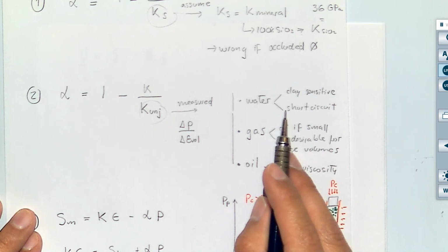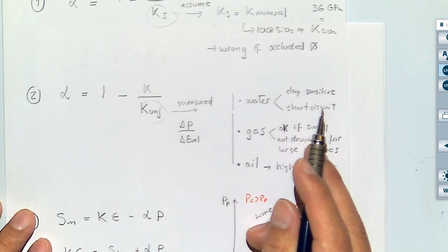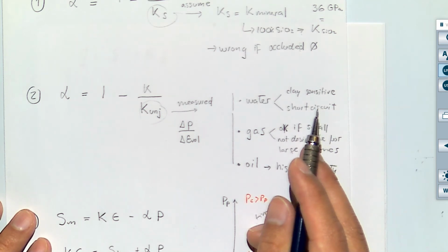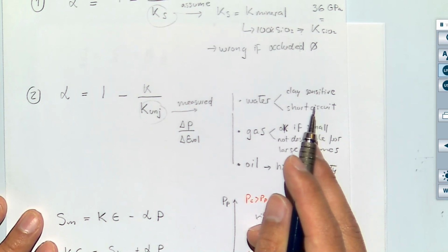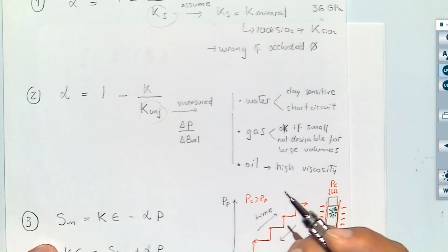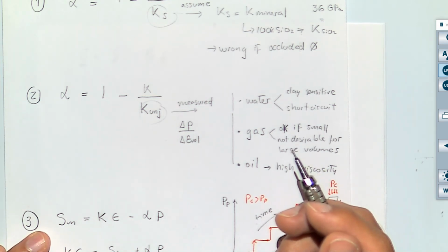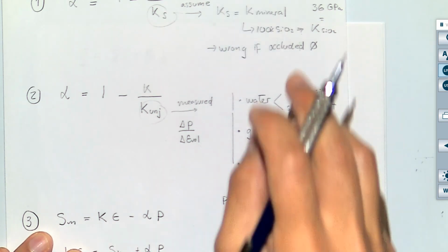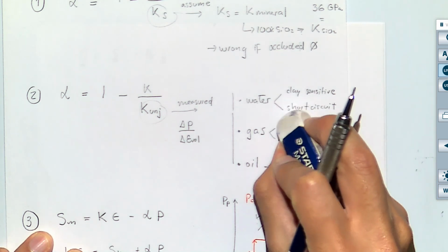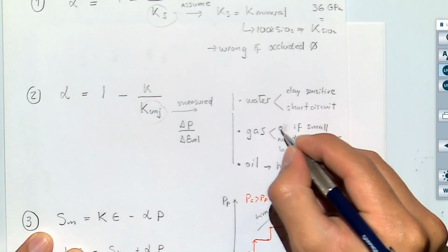So there are many rocks that have clays in them. When you expose them to water, the clay inside the rock swells and alters the microstructure of the rock. Sometimes it can break the rock. Especially if you expose a shale to fresh water, that's not going to be good, because that's going to swell the clays and probably break the rock.